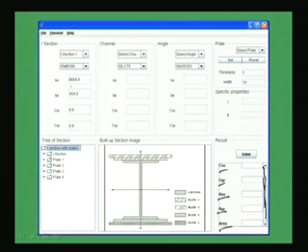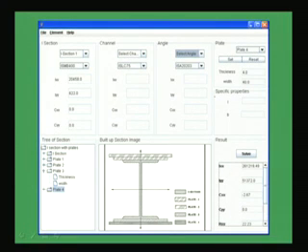Now when I am clicking, I am getting the individual properties. Say here I have given ISMB 300. So for that, what is IXX, IYY, CXX, CYY, all the properties are given here. Now with the help of plate, with providing plate, we are going to get these results.